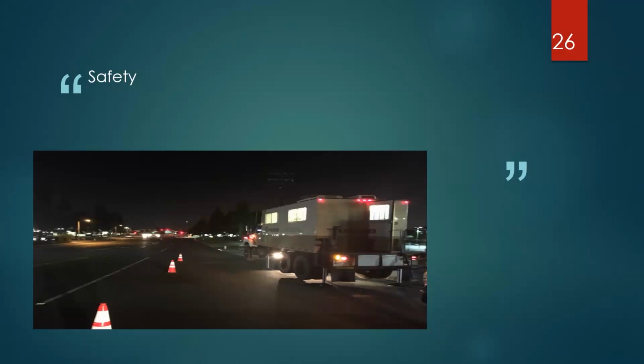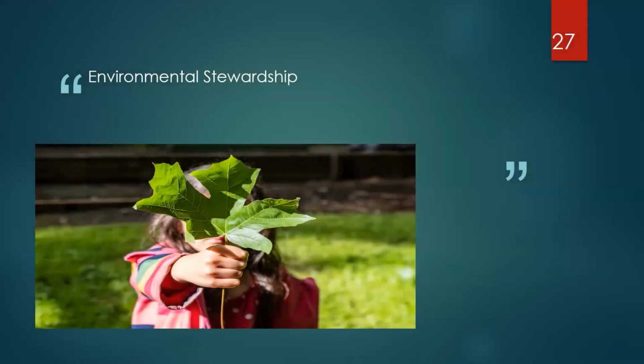Safety. Now, why this is important for every project, and of course, paramount for projects here in Southern California, as I'm sure you can appreciate and understand, but even more so for this project, because 405 is just a huge traffic load. And also a lot of that investigation was done at night. The reason for that was because we don't want to go out there and do the investigation during the day because it requires lane closure, and lane closure was just a no-no unless it was mandated for extreme conditions that required that. The preferable way and the way it was contractually agreed was that they want to do it at night. And at night it's a different environment, and CPT was much more, in my opinion, safe than doing borings next to the traffic at night.